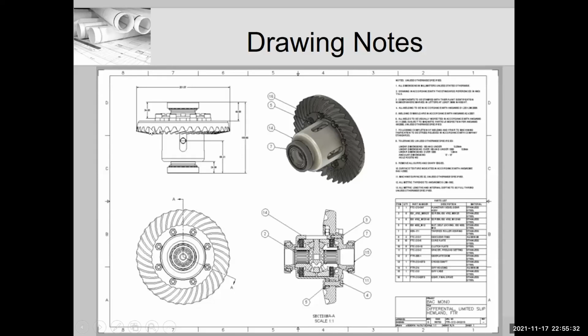Okay, so why are there dimensions here? So some of these I can understand, some I don't. This is something I downloaded off the internet, so you know somebody has done this. Let's say you put this whole thing together and its total width cannot exceed the number that's listed here. Then you want to have that. It should be a reference dimension.